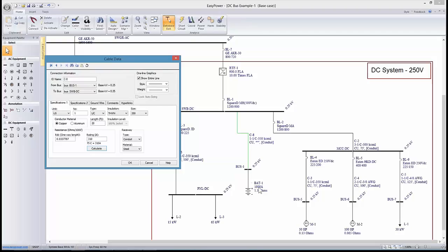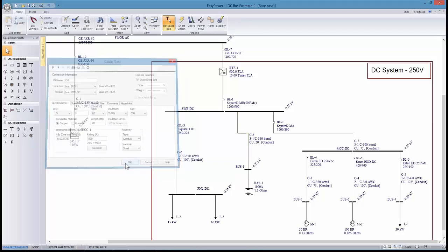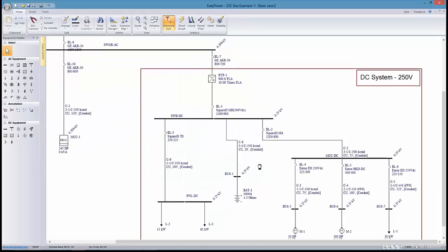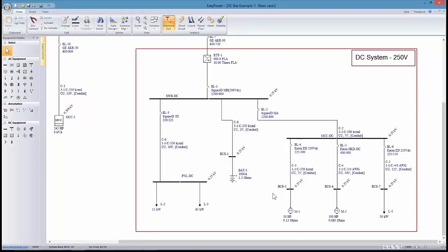Since we're setting up a 1,000 amp battery, let's go ahead and make this a 3-conductor connection, and that'll get us at least close to the 1,000 amps, assuming that we're intentionally trying not to run at 1,000 amps. Again, this is not a recommended way to design a system, but let's assume this is the way it has been set up and we're inheriting it.